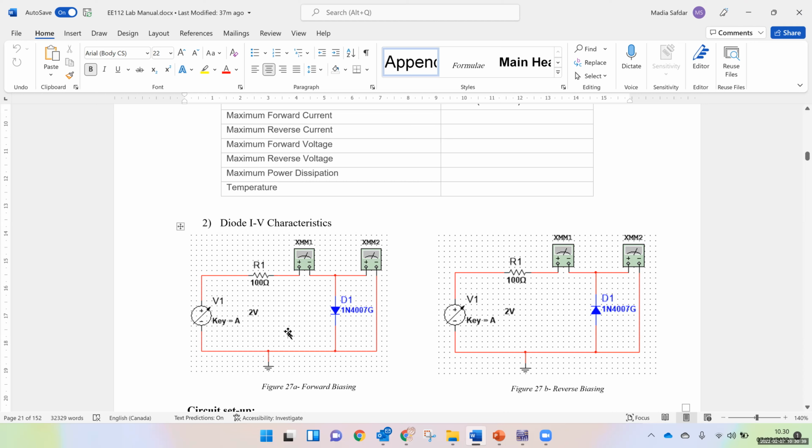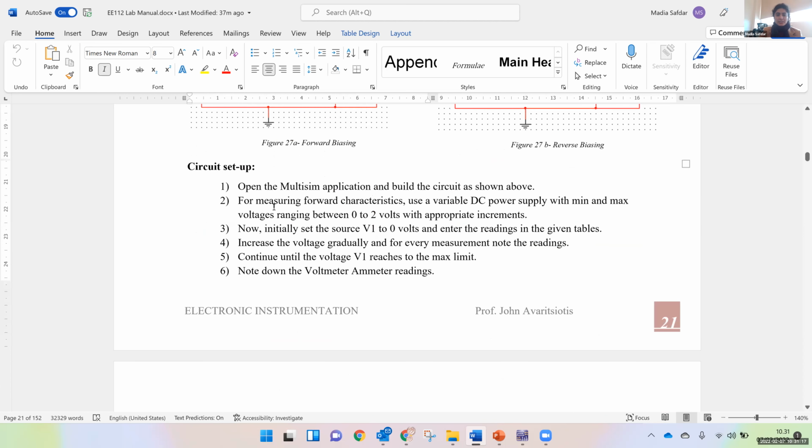See, this side is negative. This is the positive side. Always remember. So in which mode is this diode connected? Check the terminal of the supply and check the terminal of the diode. Positive with negative, negative with positive. So this is reverse bias mode. It's written also here: forward biasing and reverse biasing.